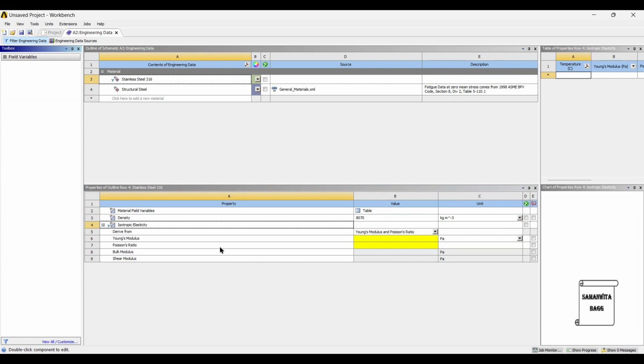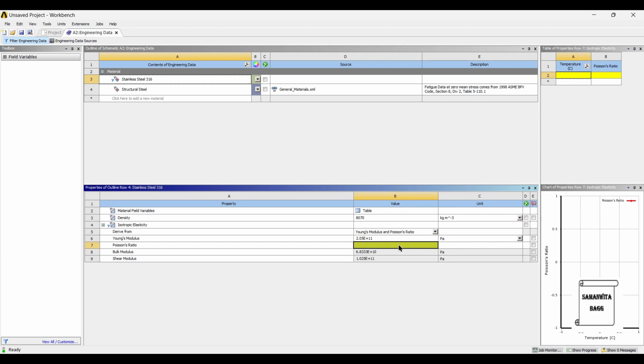Next is isotropic elasticity. The Young's modulus is 2.5 gigapascal, so it is 2.5 E9, and the value of Poisson's ratio for the material is 0.275. You can also add the value of compressive and tensile yield strength if you want to find the safety factor. Now that is not the concern of this analysis, hence I am not adding those two properties. You can check the analysis of compression bone plate static structural analysis, wherein you will find the entire analysis done.